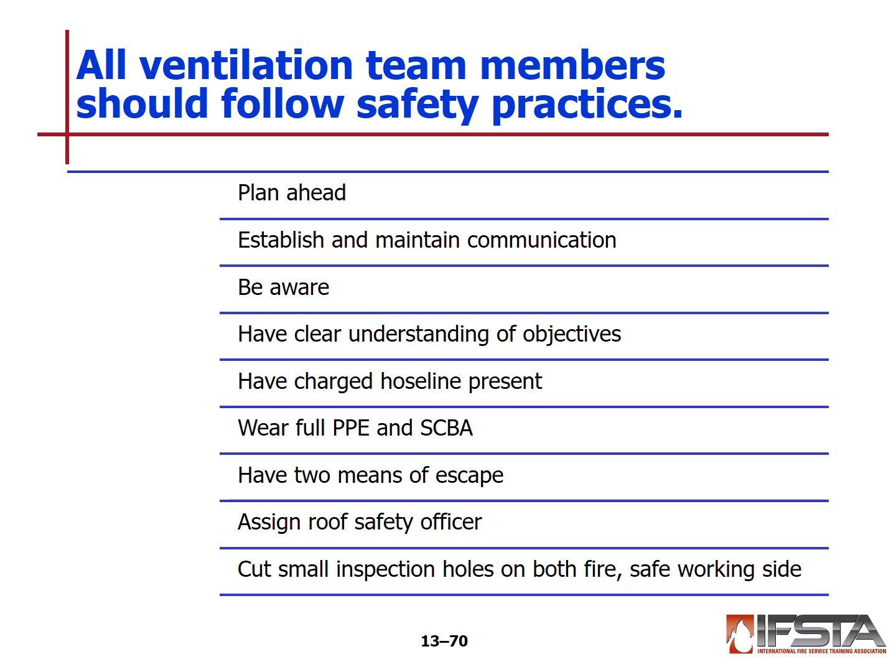Obviously, we've discussed it. When we're up on that roof, it's full PPE, full SCBA, those two means of egress. Somebody up there, we're always our own safety officers, but like I said, somebody's head's on a swivel. At any point in time, if he says no glory, operation's done, go to egress, get down. And cut that small inspection hole on both the fire and the safe working side, so that you can see what's going on.